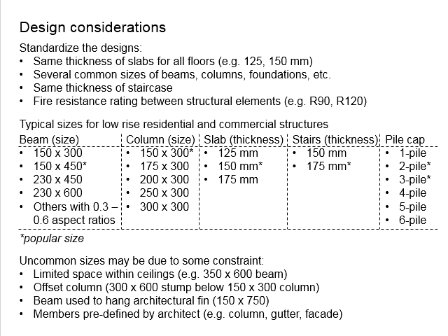You know that the ground conditions are soft because you haven't finished the construction. You will need to make sure those soft soils are able to carry weight, that the entire workflow is smooth, and you know that the concrete has its own setting time, within 45 minutes to 1 hour, by which it should have already been properly placed and leveled for sufficient workability. All these need to be properly planned. It is not as easy as you think.